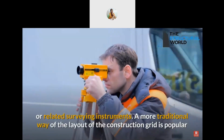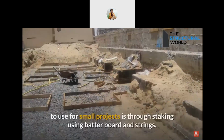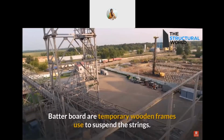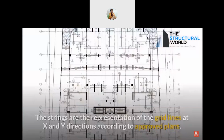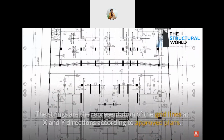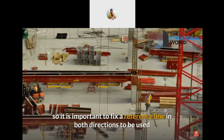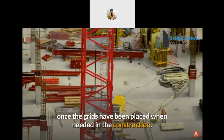A more traditional way of laying out the construction grid, popular for small projects, is through staking using batter boards and strings. Batter boards are temporary wooden frames used to suspend the strings. The strings are the representation of the grid lines in X and Y directions according to approved plans. These will serve as a guide throughout the construction, so it is important to fix a reference line in both directions to be used once the grids have been placed when needed in the construction.